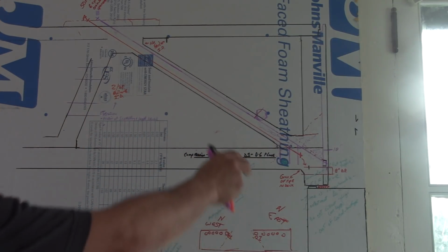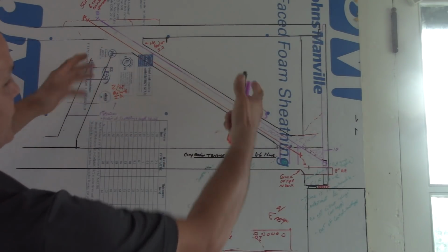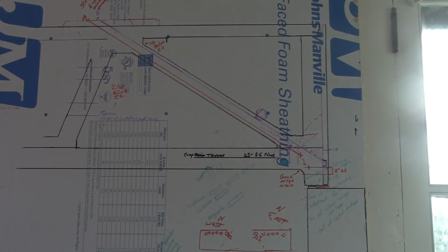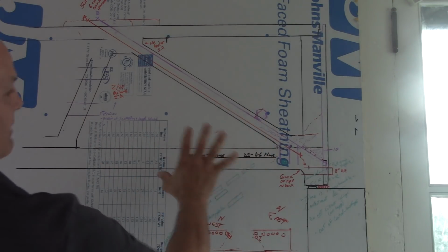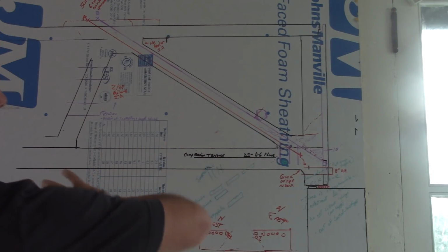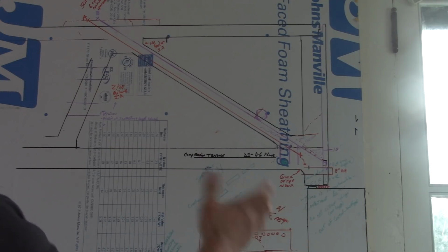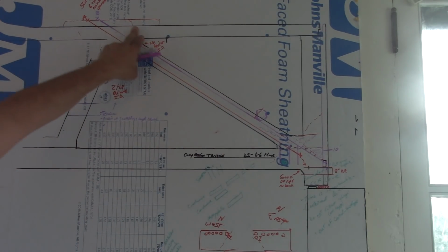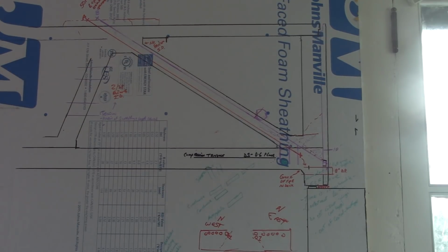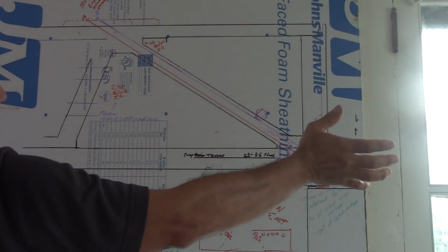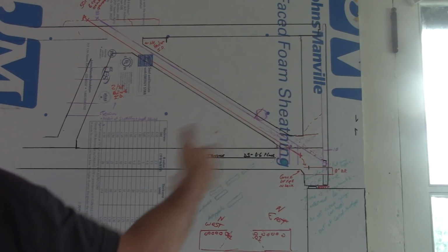It doesn't matter if you got cracks here or anything else, because you've overcalculated how much compression you need to handle the entire bridge weight, plus the 16-inch pipes that apparently might have been 1 3/4 inch thick walled, which is some mega huge weight that was going to go on top of these guys. So these cracks here, they're nothing. They're moot. There's nothing to them.